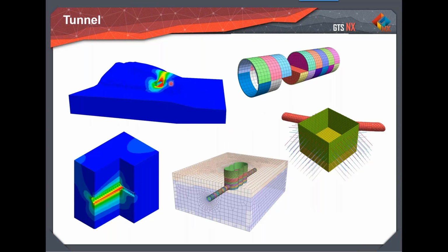So this is about the tunnel failure surface. So tunnel portal failure surface, the stability of the portal. And then we have a shaft here, and then there is a TBM lowering at the bottom. So there will be a TBM lowering, and you can simulate the TBM excavation here. And this is a very simple demonstration model wherein you have a deep excavation nearby your tunnel. So you can simulate the metro station excavation, kind of.